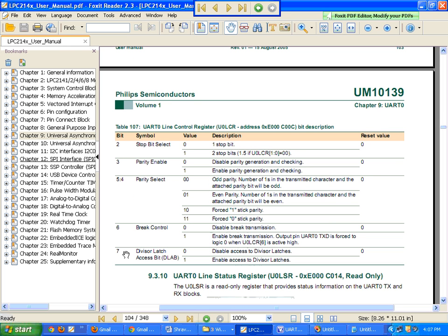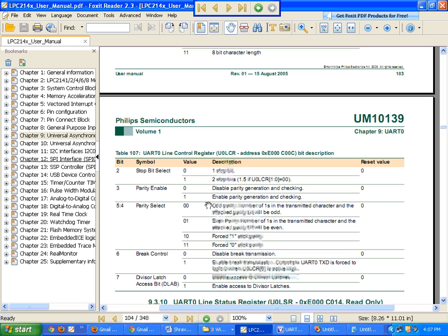The last 8th bit and the 7th. It will start from 0. So 7th bit will be 1. You should make it 1. Parity bit is to enable this parity, we don't need to enable it. This will select how many stop bits. So by default it will be 1 stop bit, disable parity, or everything will be zeros. The last 7th bit will be 1.